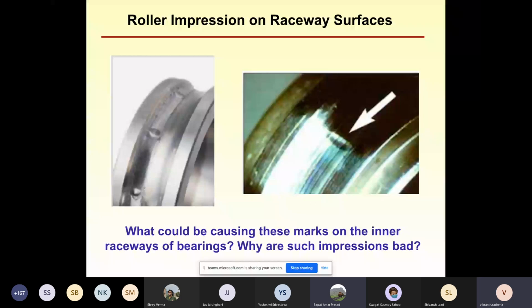Plastic deformation. Very good. So this is failure from plastic yielding of the material, which is a fancy word for causing permanent shape change within the material. Anytime you see a change in shape happening due to indentations, basically a permanent shape change in the material, you have plastic yielding. So that is the failure mechanism here. What do you think might have caused it? You said excessive loading.